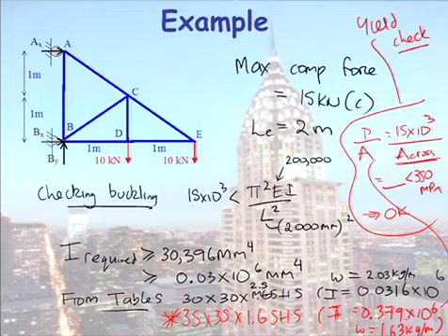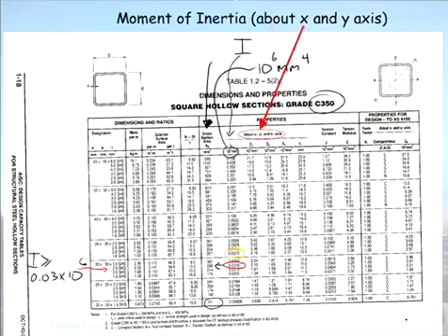Okay, so we've now checked it for buckling and yield. So be aware, people tend to, when they move up the table there, look for the first value they hit and say that's the answer there. But the more efficient section would be the 35 by 35.